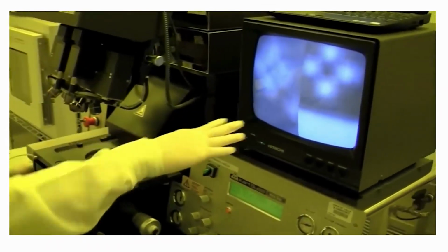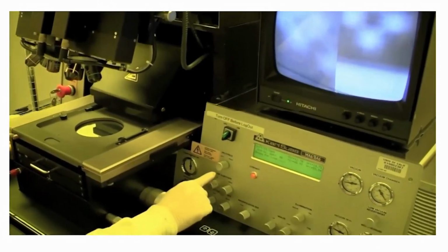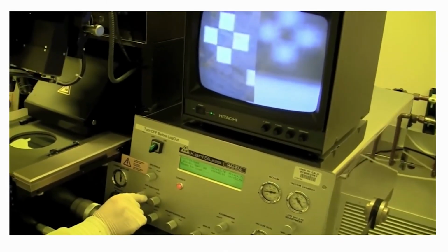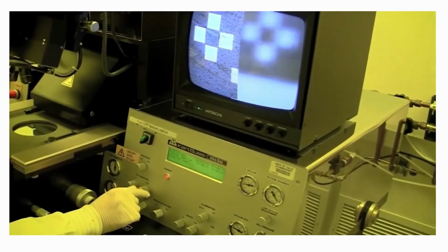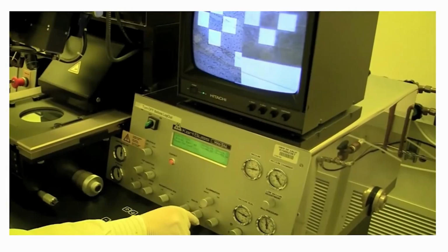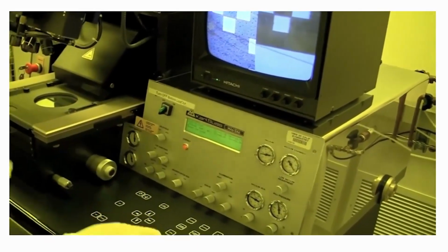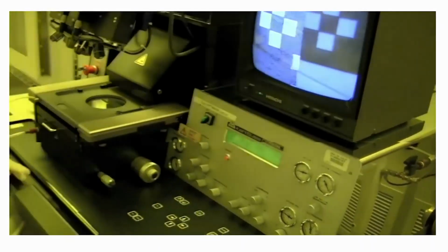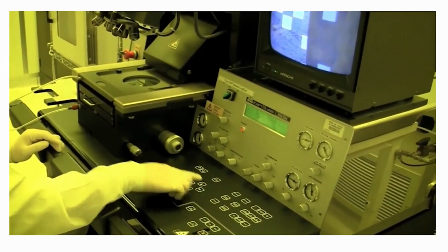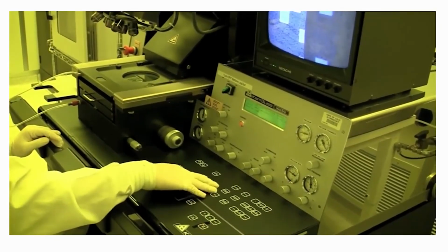Looks like we found alignment marks on the mask. So we need to adjust the focus. So you use this top straight left and right. So the left one adjusts the left, and the right one will adjust the right focus. You can also adjust the intensity. And you can also adjust the position. So if I want to move this one up and down, I would hit the right, and then I would move it up and down. If I want to move the left one, it's a similar thing.